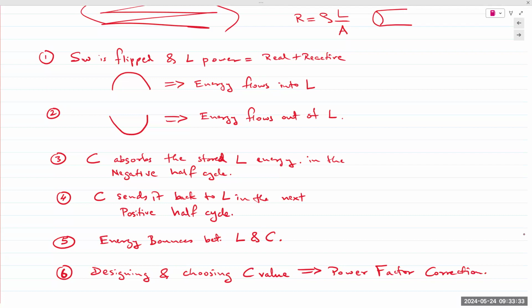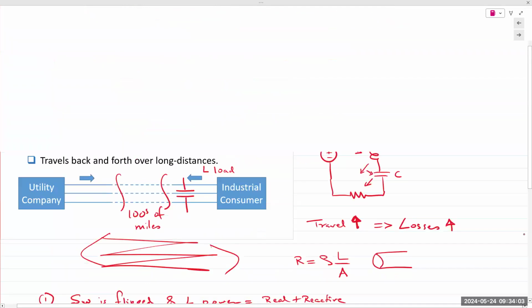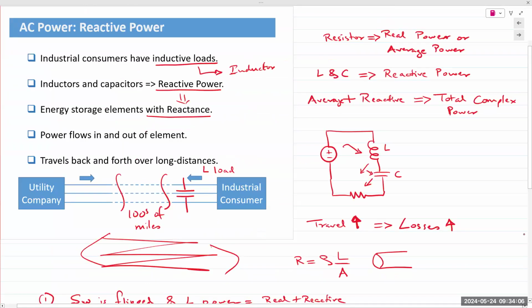That is at resonance. So at resonance, we looked at the mathematical equation where we said that the impedance of the inductor and the capacitor balance each other out, right? But physically, what is happening is that the energy that is coming from the source gets divided between the inductor, capacitor, and resistor. But at one particular frequency, that energy is confined between the inductor and the capacitor. So they don't pull any energy from the source. All of the energy goes to the resistor. So the output across the resistor goes to maximum.